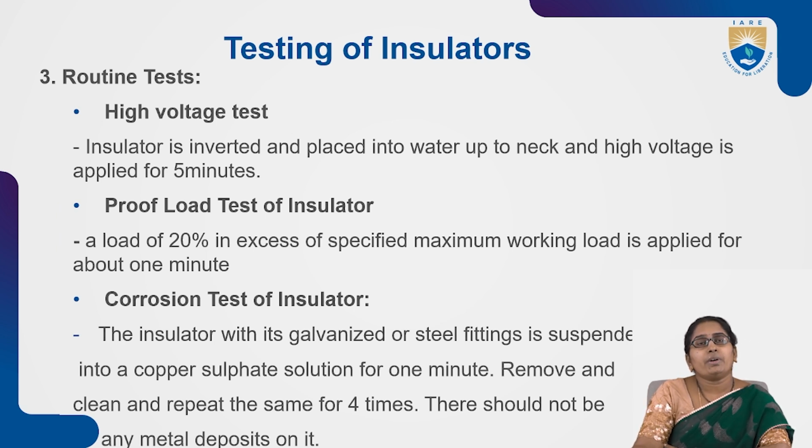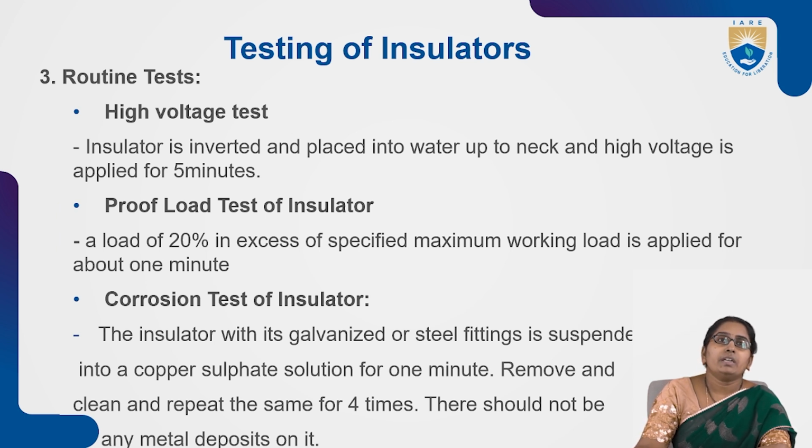And then the third one, corrosion test of insulator. The insulator with its galvanized or steel fittings is suspended in a copper sulfate solution for 1 minute. Remove and clean, and repeat the same 4 times.